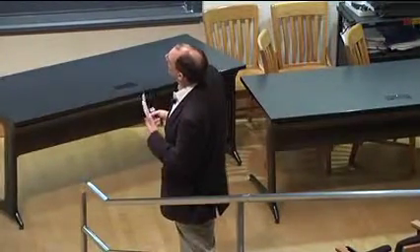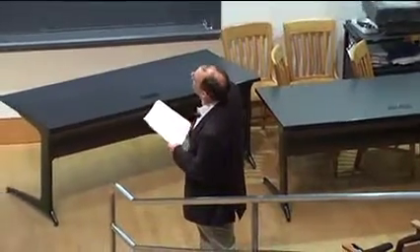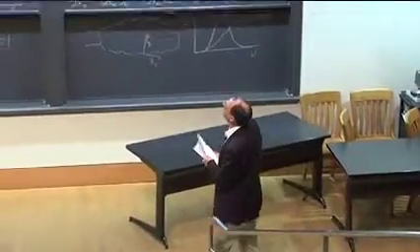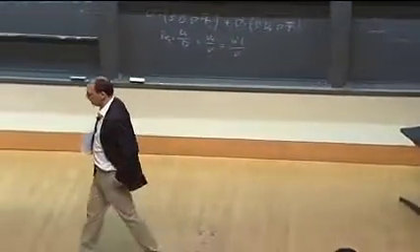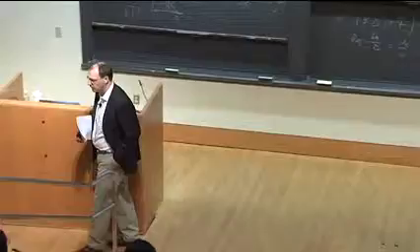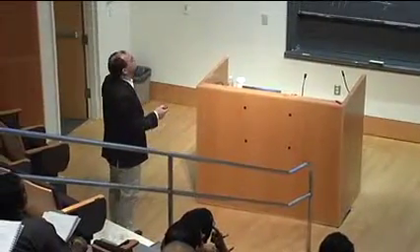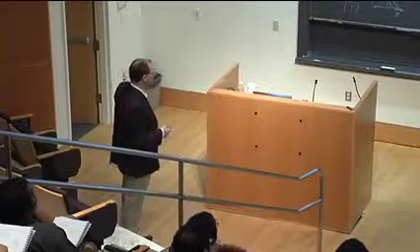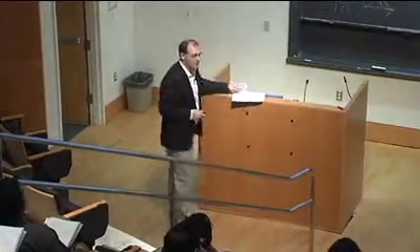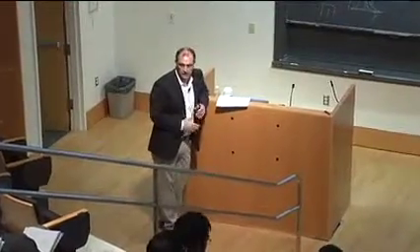Okay, so we mentioned earlier that the scalar dissipation and also scalar transport are important in turbulent flows. And so the question is, how do we model these? Important here is, we can introduce models for the scalar flux first of all. Here we use just the example of the mixture fraction as a non-reactive scalar.